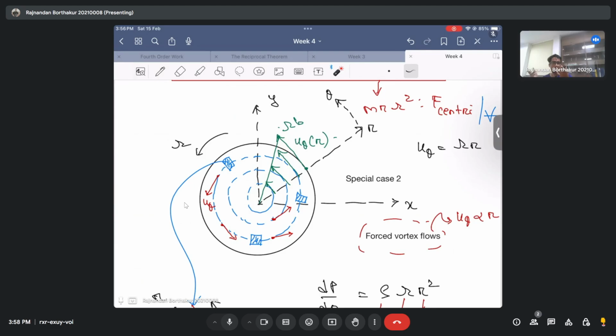It is named after the great G.I. Taylor, who worked on many of these kinds of flows, axisymmetric flows. And in fact, there is also a very famous stability analysis of these flows, known as Taylor stability. It is shown that if the rotational velocity of the cylinder exceeds a critical velocity, then this flow gives rise to instabilities, and these are known as Taylor instabilities, named after again the great G.I. Taylor. We will not look into these instabilities now, but later on when we look into hydrodynamic instability, we will. Just for know-how, I say how rich the literature is in terms of Taylor-Couette flows.